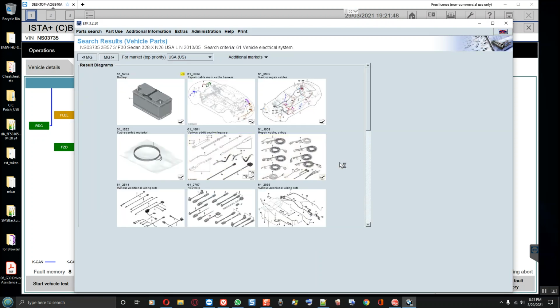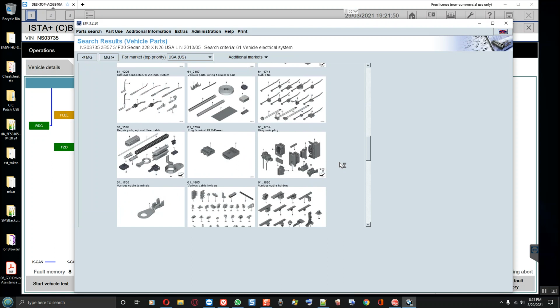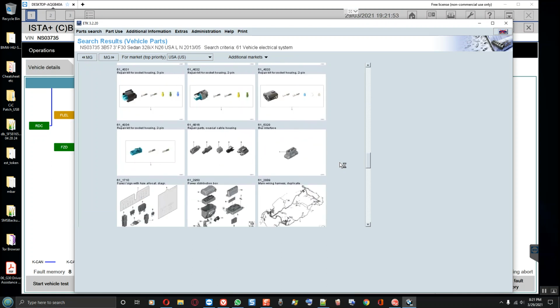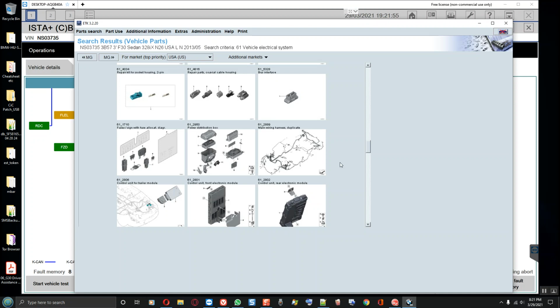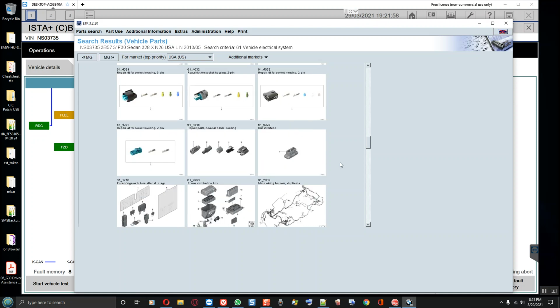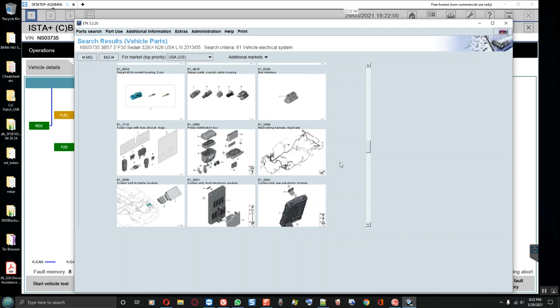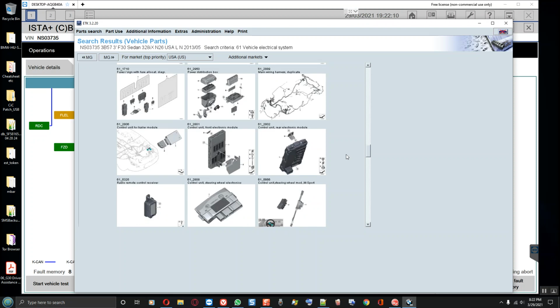I'm gonna try to find something for the integrated chassis management for this car. I'm gonna see what ETK is saying with the options. I remember the vehicle order of the car, so I remember what was deleted. What I'm gonna try to do is see what ETK says, because they give us different choices. If LED lights come with adaptive lights, it will say this ICM you must install, and then I'm gonna compare that with the part number of the ICM that comes with the car.